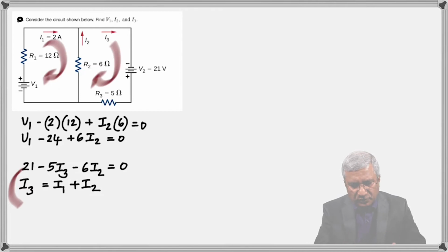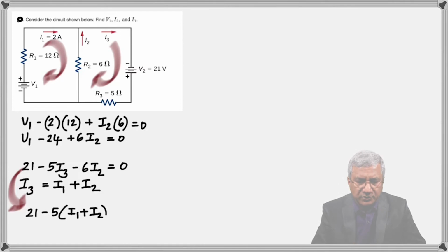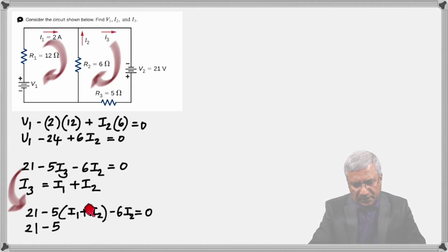So we get those two equations, and then when we apply the junction rule here, as I already explained, you get I1 plus I2 is equal to I3. So we just need to solve these three equations to find the currents. And we can do that in different ways, but this is what I do. For I3, I am substituting I1 plus I2. Right here, instead of this I3, I'm substituting I1 plus I2. Distribute that.